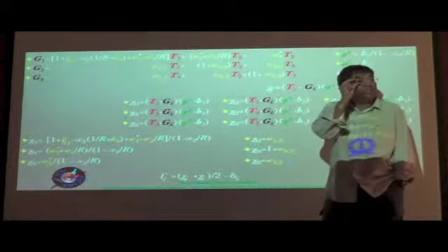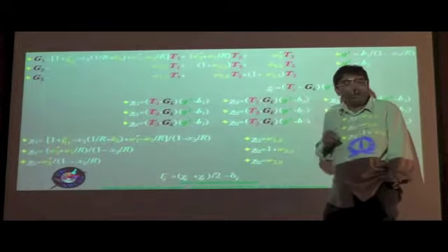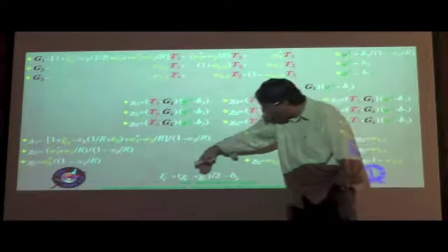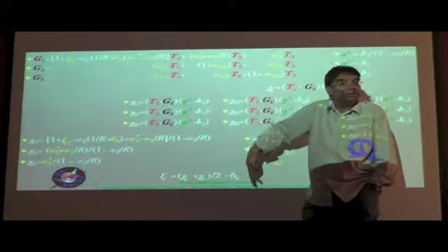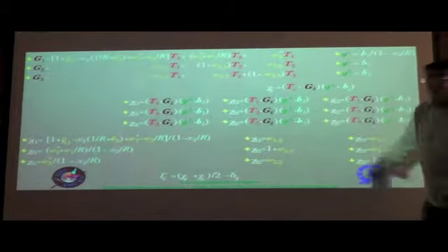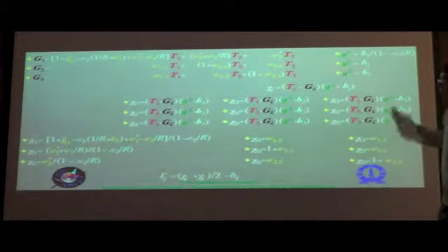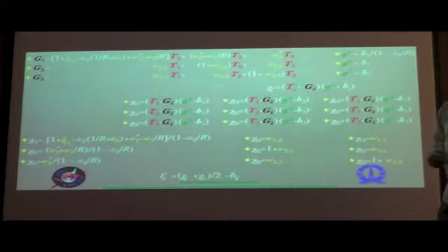So this is what you have as expressions for all of the chi's. Once you have the chi's, because we are talking about a small local rotation theory over here, because classical beams, isotropic, is what we are dealing with here, only the symmetric portion of this chi matrix is useful for us. We have 9 independent components over here, but we will be basically taking the symmetric portion of that, so only 6 quantities of interest would be there.